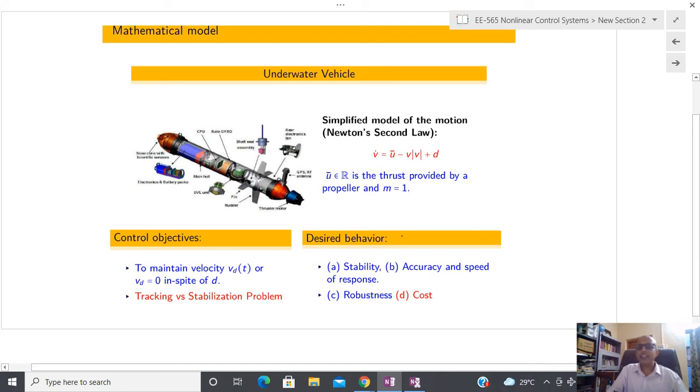Now you can see that this system is no longer linear because here I have a non-linear term. So I cannot talk about the quantitative behavior of this system. Quantitative behavior means that if you have a linear system, you note rise time, settling time, these kinds of things. After that, in the frequency domain, you see where the open loop transfer function lies as you increase the frequency from minus infinity to plus infinity. But I cannot do that here, and for that reason, whenever you have a non-linear system, you have to talk about stability not in a quantitative way but in a qualitative way.